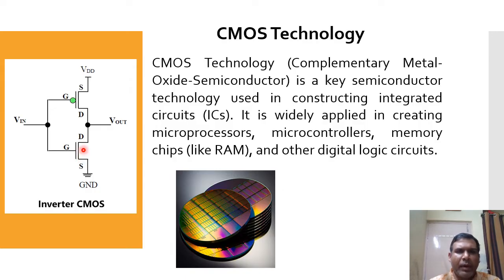When we combine these two transistors in series, it becomes a CMOS circuit, where the gate terminals of the P-type as well as the N-type MOSFET are short circuited. This terminal is known as the input terminal, and when the drain terminals of both transistors are short circuited, that terminal is known as the output terminal. So a CMOS device consists of two transistors, one input and one output.